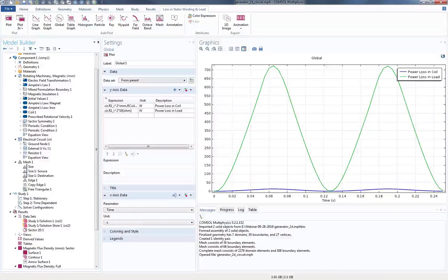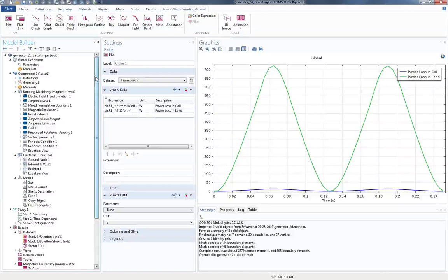So there's a question from Richard. Is it possible to model BH curve temperature dependencies? Yes, COMSOL can actually handle BH curves that are temperature dependent. Now, in this case, I'm not considering any temperature dependency in the BH curve. But if you would like, then that will be two-dimensional data with a dependency on the temperature and BH relation. So that can be done, yes.